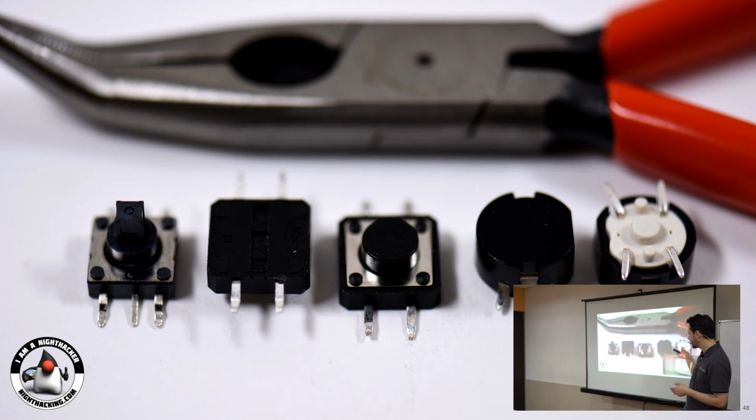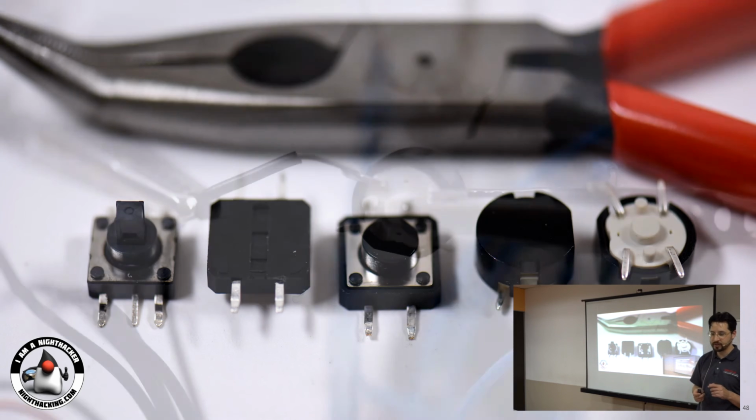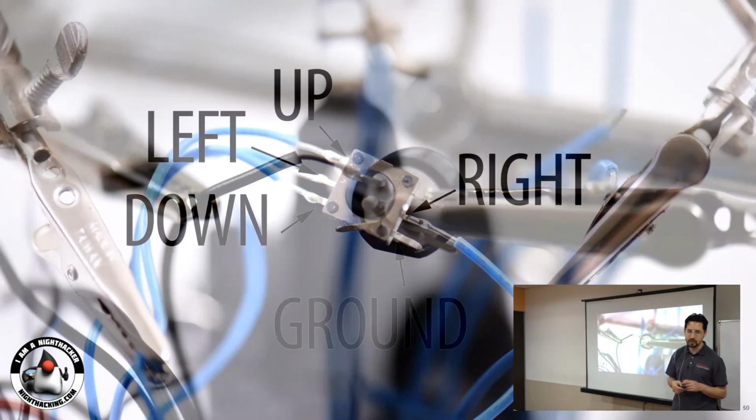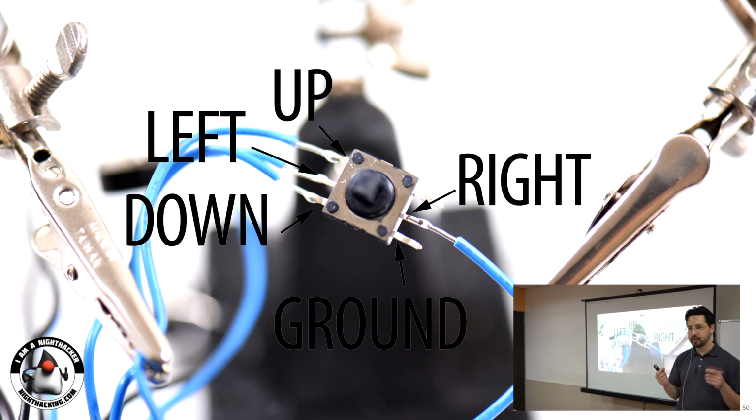Here are the buttons. I just fan out the legs to make it fit a little bit flatter inside the case for space, and soldering to the buttons directly. So this way, since you're directly soldering connections, you don't need a circuit board inside of it.